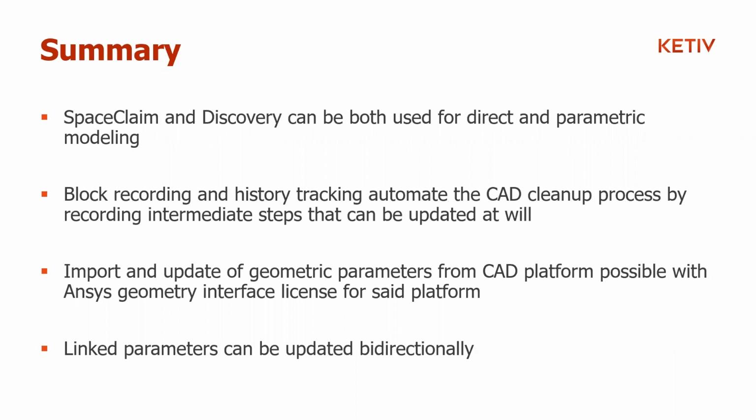So I used Autodesk as an example today, but you could set up parameters in your native CAD tool, use the prefix ANS and DS and import them within Workbench, and then maintain that connectivity while you perform the steps for geometry cleanup.